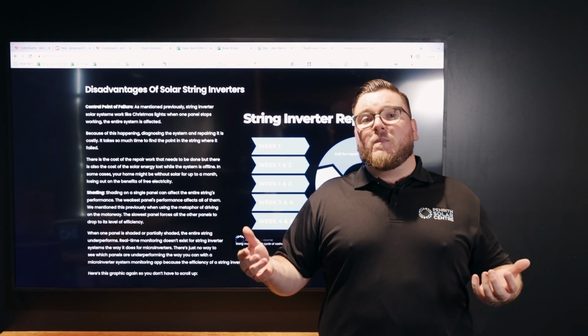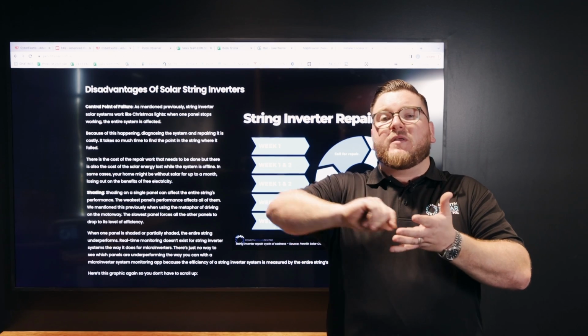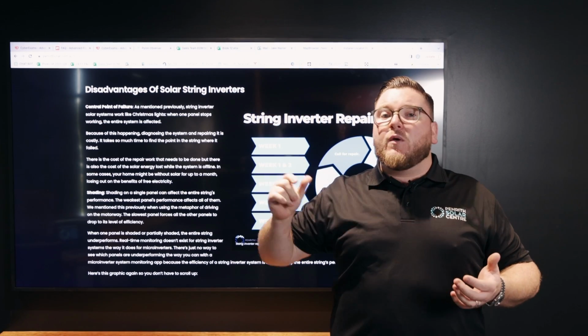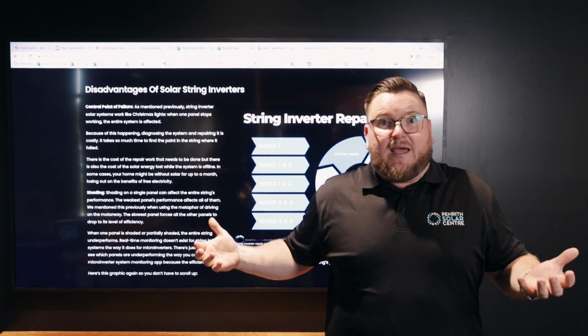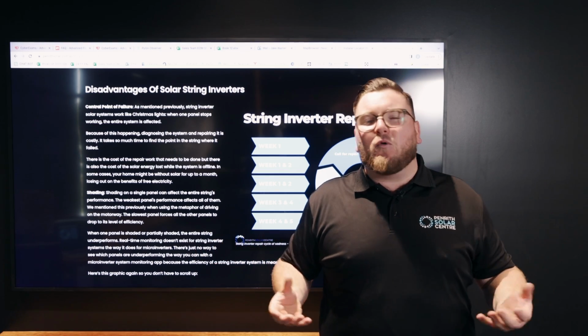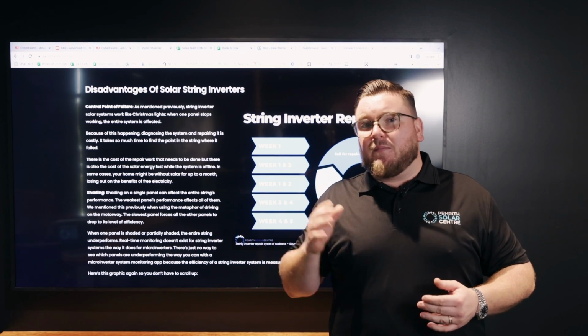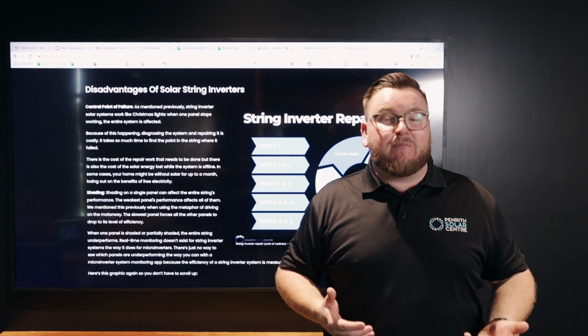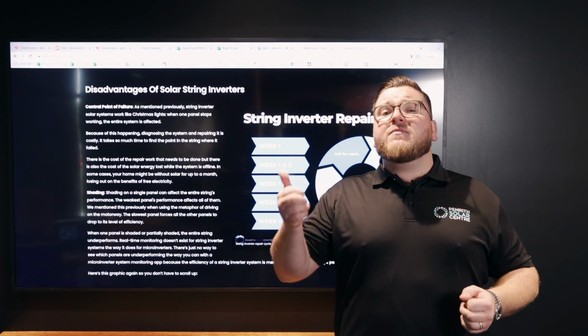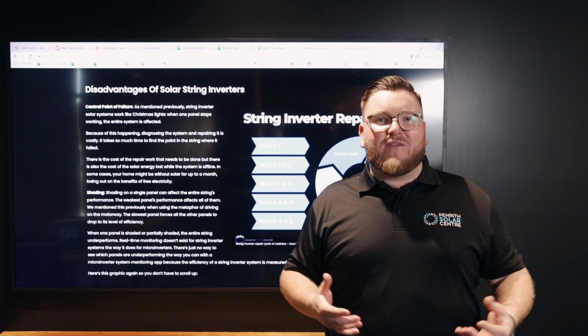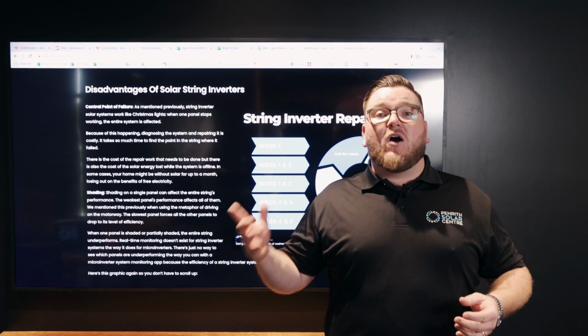which form part of your solar system. For example, the type of cable that runs from the inverter to the roof. You know it's not genuine string inverter cable. Like, what actually is this cable? I bet you probably can't even get the brand of it out of your installer's mouth, because they won't actually know. MC4 plugs are one of the next biggest failure points, as well as DC isolators.